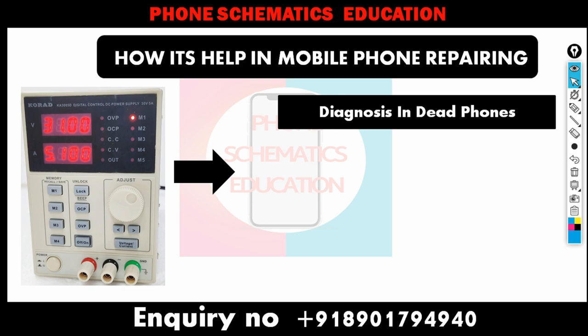When you connect the DC power supply with controlled voltage and controlled current, for example 4 volt and 3 amp, to the mobile phone motherboard, it helps the diagnosis: first, whether the phone is on or off without a battery, obviously. Also whether there is a fault in the motherboard or the battery. Also look at the current, or you can say ampere, sequence.